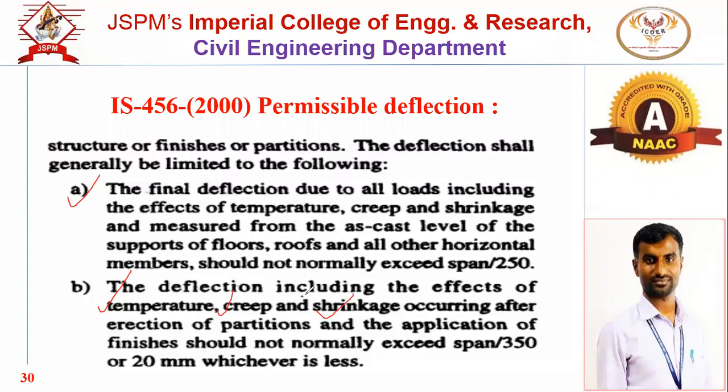It may also be the stresses or deflection induced due to the erection of steel structural members or due to the application of finishes. Means if you apply plastering or pointing, those are finishes, or if you have performed the flooring, that is also finishes. So your deflection should be restricted to L by 350 or 20 mm, whichever is less.